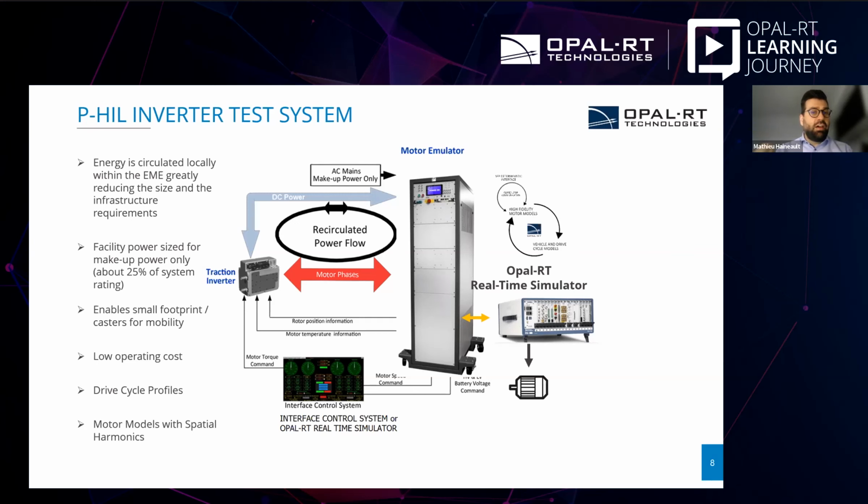That allows you to have fewer losses in the system, and you don't need a physical high power connection in your system. You can lower the specs of your lab's capabilities. Also, all racks from DNV are on casters, so you can move them around. That can be an advantage because a bigger system can be decoupled and used as two separate entities, and then be connected together again for bigger power capabilities.